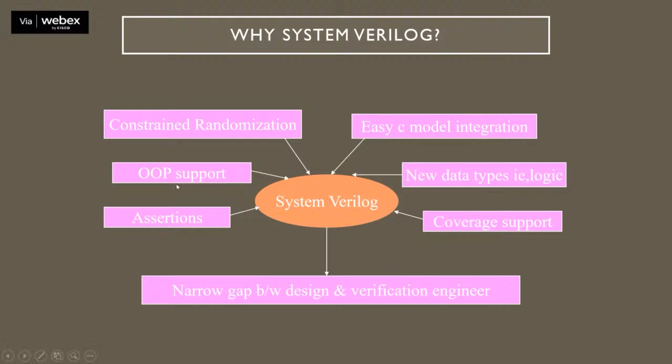Now we need to obtain 100% functional coverage. That is, you want your design tested for all possible conditions and all possible stimuli. Once it has been tested, then you can say the functional coverage of 100% has been obtained. To do that, you need stimuli that are generated randomly and can take all possible test cases.